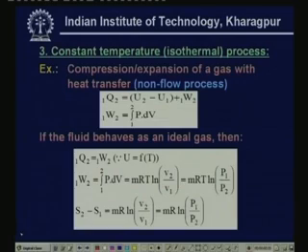And for this process, the governing equations for energy, for work transfer, heat transfer and entropy transfer are given here. For example, this equation is nothing but your first law of thermodynamics for a non-flow process. And since you have volume change here and pressure also can change, the work done during this process has to be obtained by integrating this process from 1 to 2. And so you must know the relationship between P and V in order to perform this integration and find out the work done. Of course, the process has got to be quasi-static, or quasi-equilibrium, otherwise you cannot perform the integration.